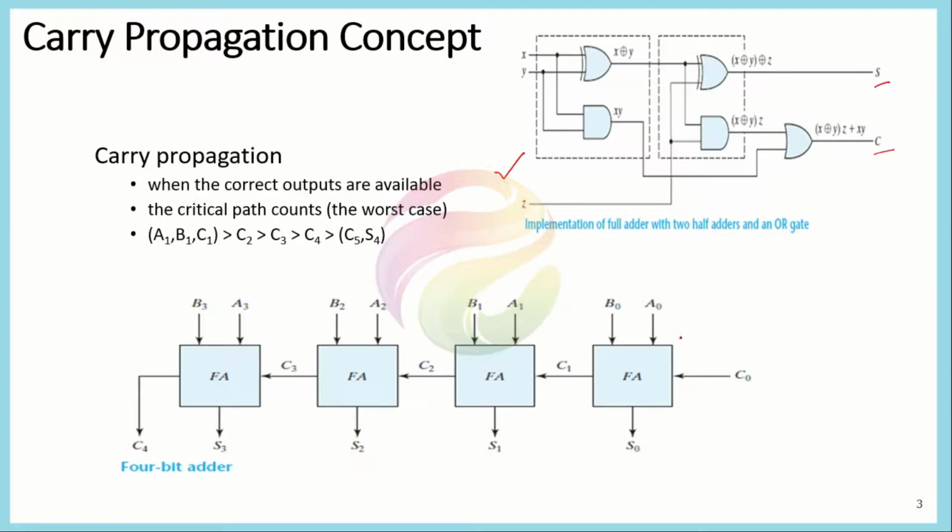From the first column, if a carry is generated, then that carry is added to the next 2-bit addition, and from that, if some carry is generated, this carry is added to the next full adder. Similarly, if the third full adder generates some carry, it will be added to the next full adder. And if there is an overall carry, then that would also be generated separately. Each bit here, S0, S1, S2 and S3, represents the sum of the two numbers.